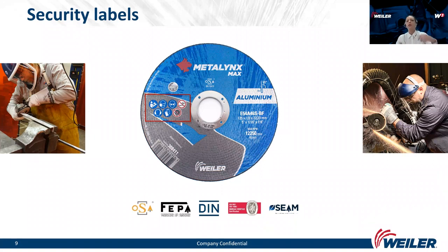So wear safety clothes, safety boots, protect your eyes and ears, wear gloves, and also wear a mask if needed, and try to keep your workplace clean. Specifically, for instance, when working with aluminium, lots of people use some waxes to make the work easier, and in the long run this can cause the floor to become really slippery.